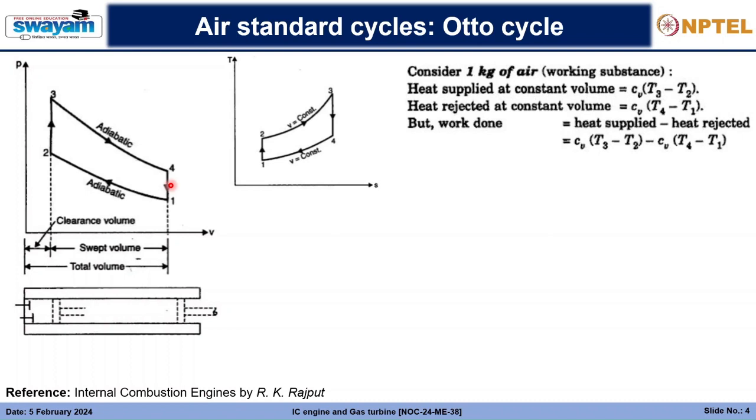We needed that heat but we cannot get it, because the efficiency always has to be there. And even if we could somehow burn the whole gas, there is another problem: some amount of gas will not burn. Unburnt parts are also being expelled out, so that is a loss. We are bound to get some good amount of work output, but we will not get it because of such defects in the system. So that's where the heat rejection process, 4 to 1, takes place.